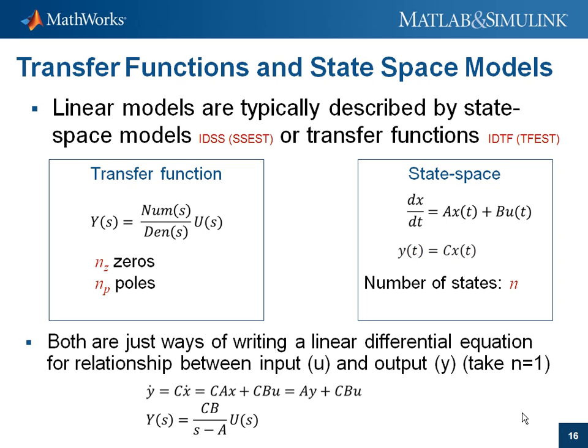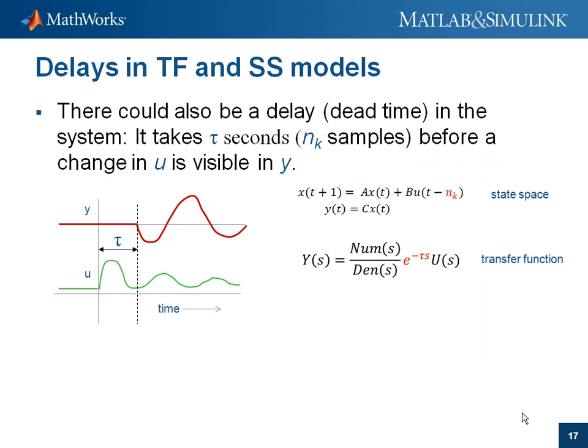Actually, the transfer functions and state space models are two sides of the same coin. They both describe the model with linear difference and differential equations, and thus cover the same set of relationships between input and output. The difference is how they are parameterized in terms of polynomials or matrices.